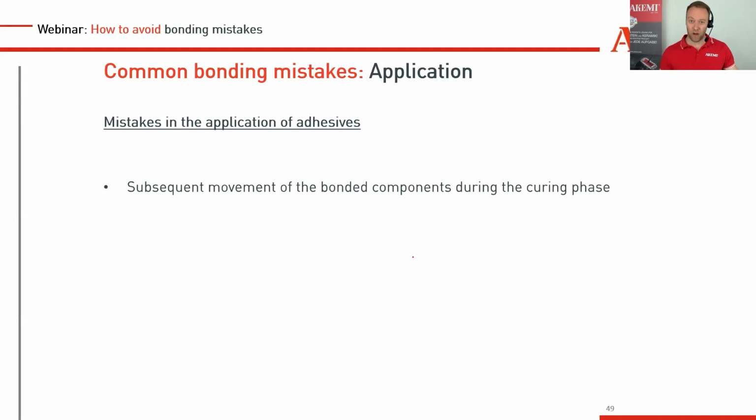This is the problem because, I will show it later to you, when you have put the glue on both sides of your substrate, you press it together, it's all good. And then you start opening and closing it and moving it. First, you will suck in a lot of air. It's like a vacuum you create. There will be some cavities, some lines of air, which you suck into the bonding seam, and this could cause problems later.